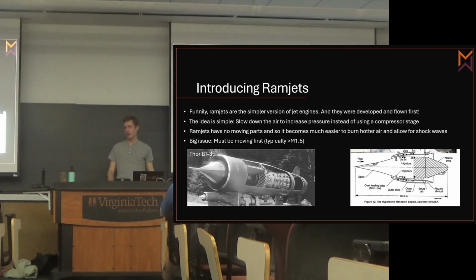Jet engines have a compressor, right? We have to get our air, it's going to be slowed down, but I need to build up pressure so I can burn it and spit it out the back. If I already have all these shock waves, we're doing all this work, let's just use the shock waves. So that's all the ramjets are doing, is using these normal shocks.